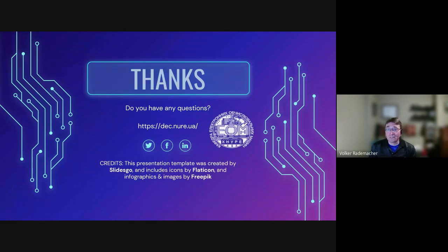If you, on the other hand, want to create 10,000 pieces of this product, a pre-made module would be way too expensive. So you would be looking into a longer development time, but you would be looking into a cost-optimized design. So you might be using BGA packages, which are notoriously hard to prototype with.